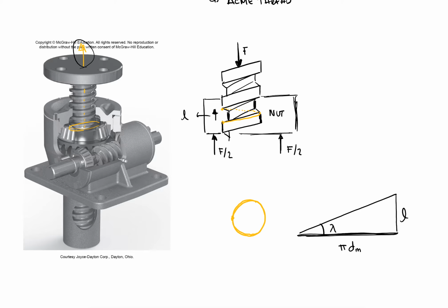Okay, so basically from this we can draw our forces. There is a force going down in the vertical negative direction, F. There would be a normal force going perpendicular, 90 degrees with respect to the surface, N. There would be a friction force that also has to be overcome because there's going to be friction between the nut and the screw itself, and that could be modeled as mu N, or I think the book uses lowercase f N for the factor of friction, f.